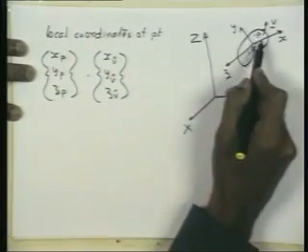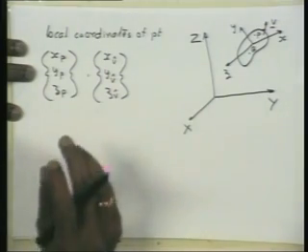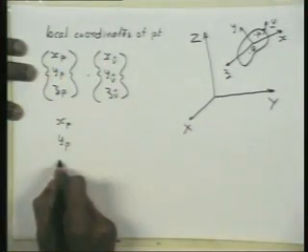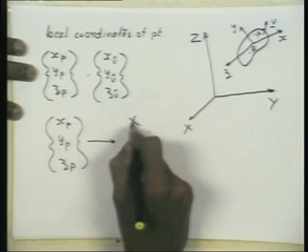So now with this we can define what we are talking about. What we are talking about is basically a set of variables by which a body can be located and oriented, which essentially means that given the values of those variables, we should be able to find out the position of every point on the body and every vector on the body, right? Which means given the location of a point P on the body, xp, yp, zp, these are the local coordinates, we need to find its global coordinates. That is, given xp, yp, zp, the local coordinates, by some means we should be able to find its global coordinates.